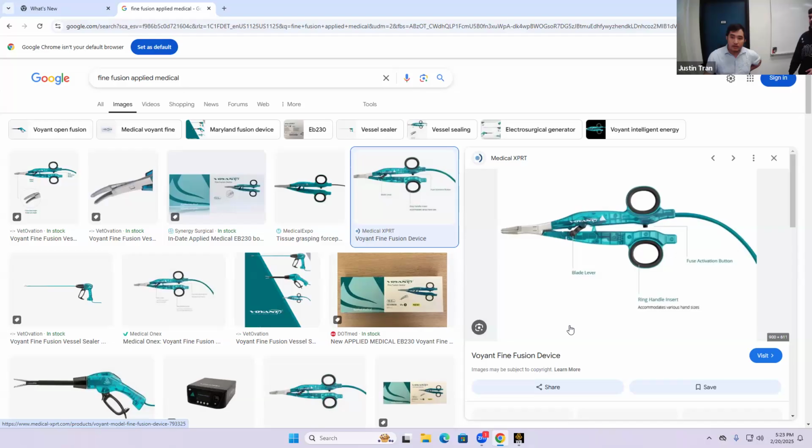So if you drop this into ANSYS and theoretically, you bring these two things as separate parts in the assembly, then you would have to define how this connection would be defined or how ANSYS is going to handle it. By default, everything defaults to, well, we're going to talk about today actually. If you have two parts and they're close together, ANSYS is going to assume that they're mixed together. That's what's called a bond. But you can change that, and instead of having the bond there, you can have a frictionless bond, or a no separation type of contact as well. And that's going to change how many reaction forces go there.